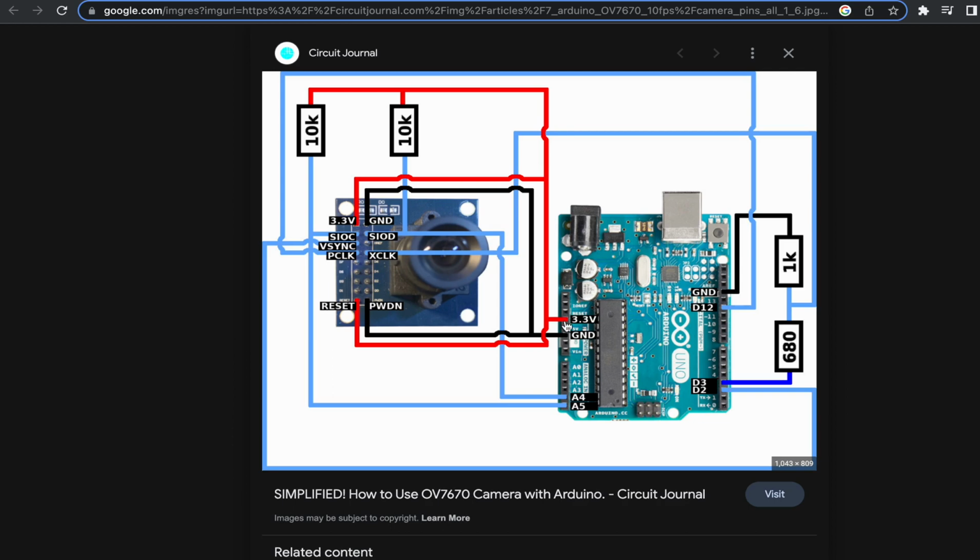We can see the 3.3 volts, right? So the connectivity should be 3.3. In the data sheet of this, that information will be clearly stated. We can see where the wiring takes place to 3.3, and the same is given to the reset pin as well.